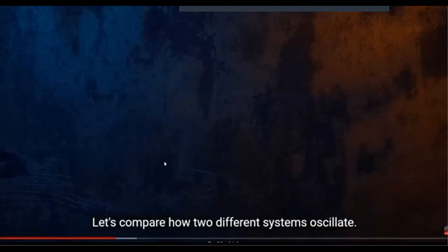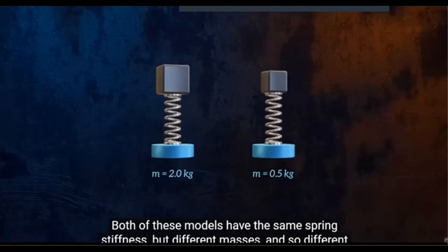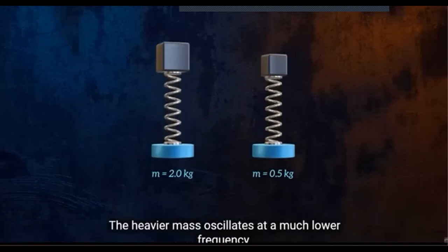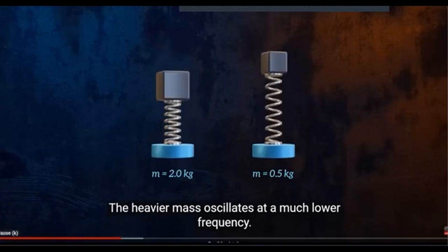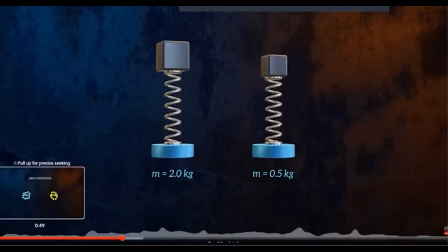Let's compare how two different systems oscillate. Both of these models have the same spring stiffness, but different masses, and so different natural frequencies. The heavier mass oscillates at a much lower frequency. Why am I showing this to you? Because we have a drum in the washing machine, which is rotating. It has a certain mass. We also have not only the drum, we also have the pulley as well as the belt tied to the motor, which are going to have different mass. Which means, let's see the simplest one.